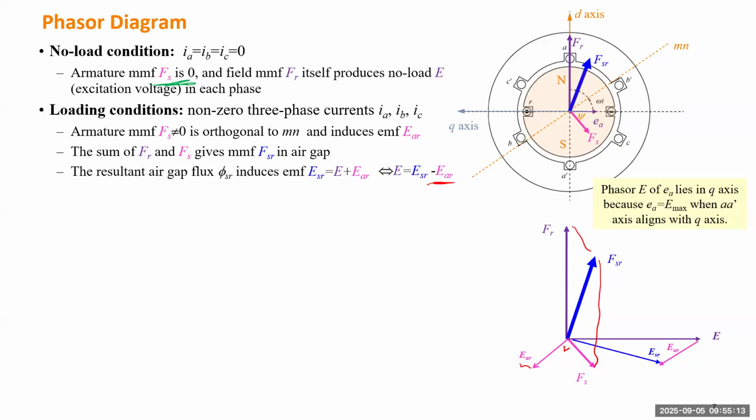So if we want to make this longer one the internal voltage, because our goal is to have the generator modeled by some equivalent circuit, this internal one will be E. That doesn't change with the external load. The terminal voltage can be different because the generator may have some internal impedance.